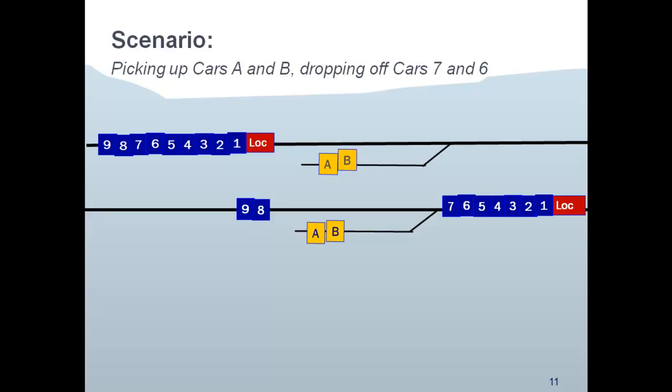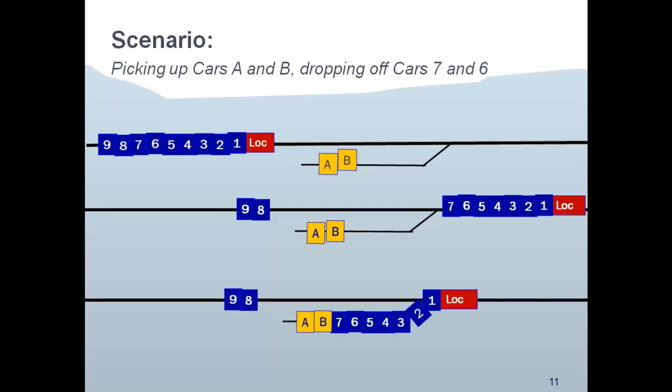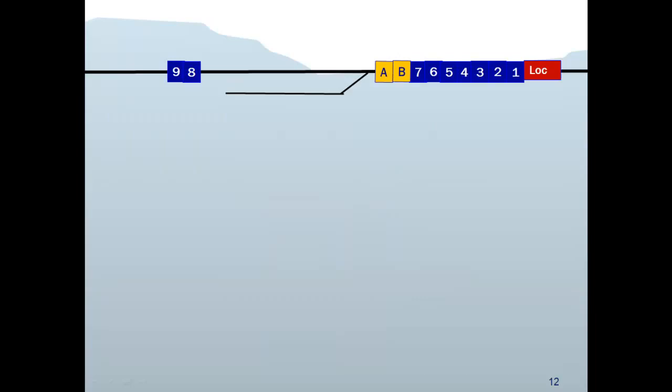The train moves forward, throws a switch so that it can access the spur. The trainman may need to get out of the train to unlock the gate to the industrial area. The trainman backs up the train, couples up A and B, releases the handbrakes on A and B, and connects them to the air brakes on the train. The train then moves back onto the main line.